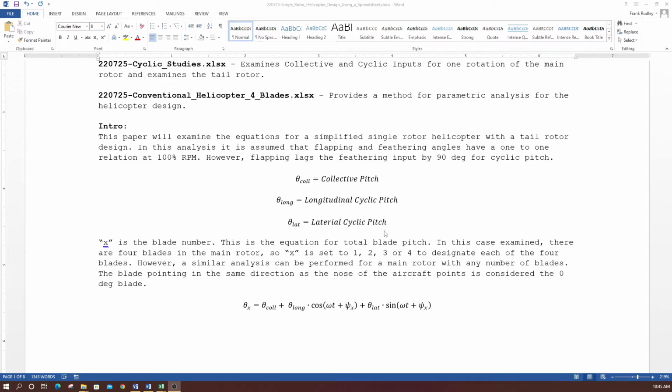What it provides is the forces. It provides left and right forces, lateral forces to overcome the drag of the aircraft. And the longitudinal would provide our forward motion to overcome the drag of the fuselage mostly. And collective pitch is our vertical input that allows us to overcome mostly the weight from gravity and allows us to make the helicopter go up and down.